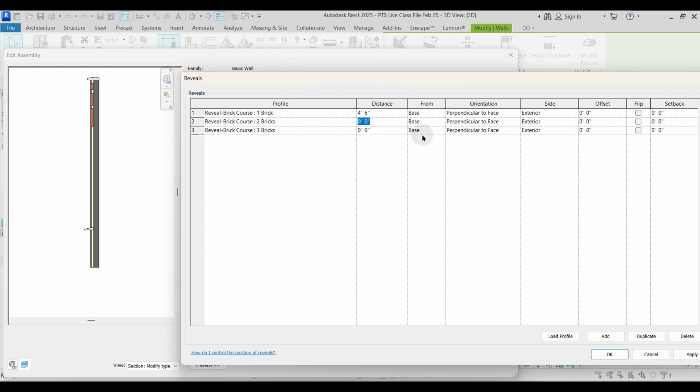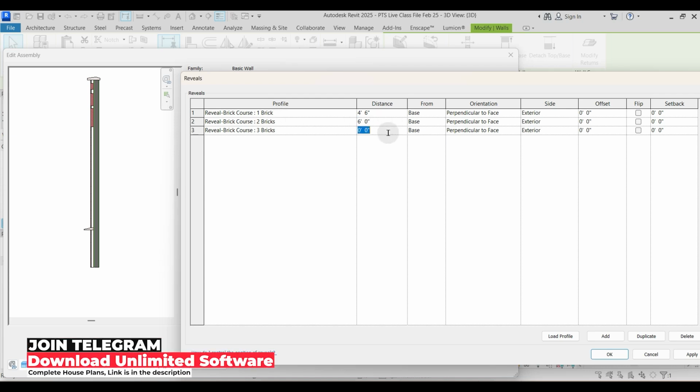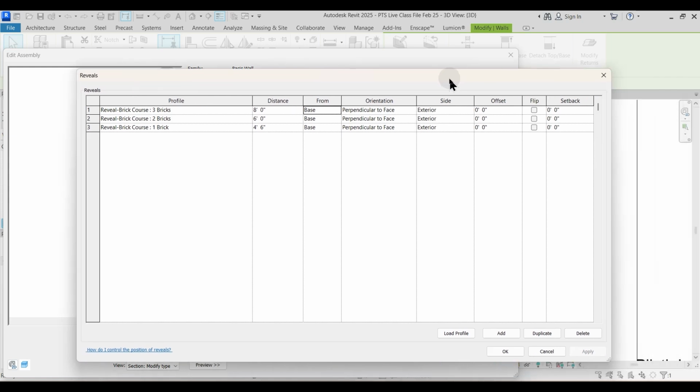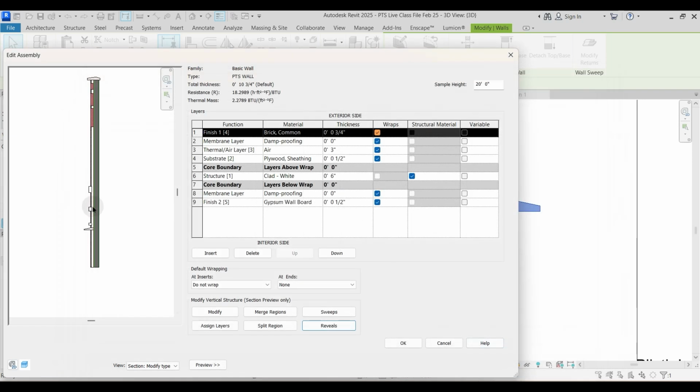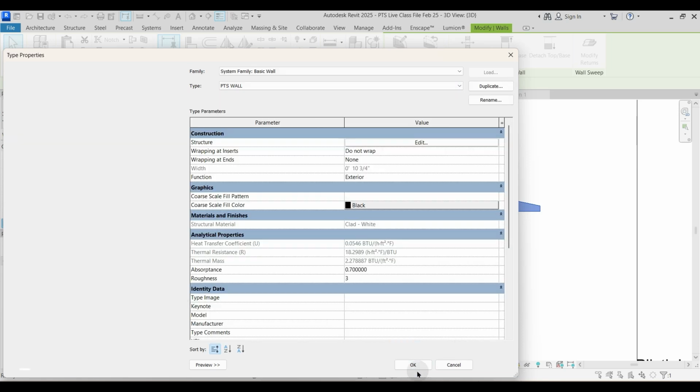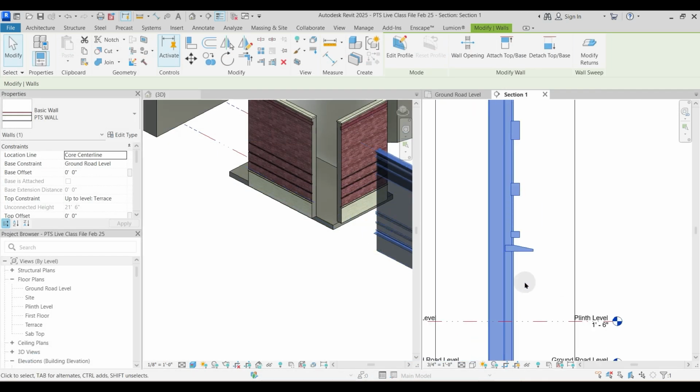Okay. One brick, two brick. मतलब ये होगा 6 फीट और ये होगा 8 फीट. Apply. Clear? Clear, everybody? And offset. Right now, don't worry about this offset parameter in this case, because it is just deducting that much part from the wall. So okay, apply, okay, and yes.